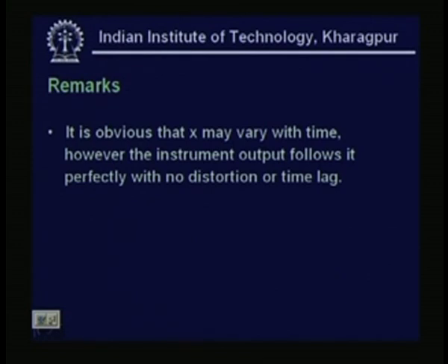Whatever the input in the system, it will immediately appear at the output without any phase lag. It might be step input, ramp input, or sinusoidal input. So, that means it is a zero order instrument.